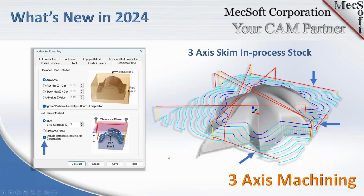Now, for 3-axis enhancements, this is a pretty good enhancement here. If you look at where the arrows are, we're looking at horizontal roughing, and we're looking at the clearance plane tab in the cut transfer method. So the clearance plane definition in this example is set to automatic. And then below that, we have the cut transfer method set to skim, but we've also added a checkbox here to include the in-process stock in the calculation of the skim clearance.